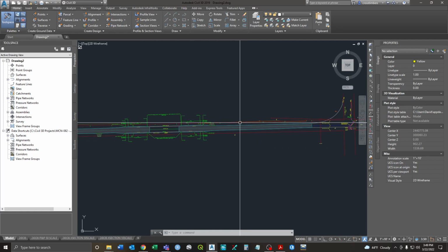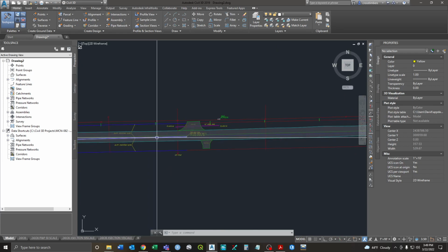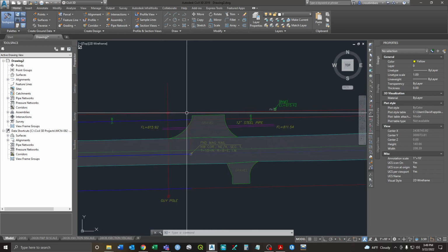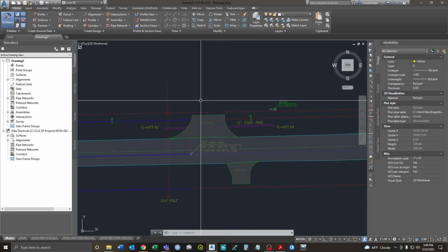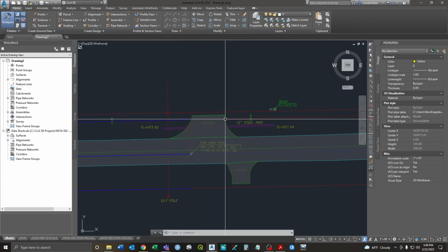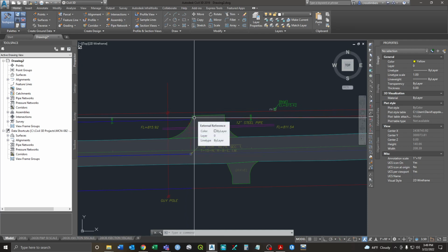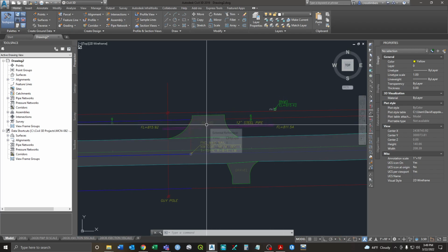So those gravel spots there, he doesn't have those on the map to do. Or do I do those gravel spots as well? So this is where you're going to have to talk with him on the driveways. I don't think he marked any of the driveways. Maybe not. But we'll talk with him and say, hey, look, there's a lot of these driveways that are over the right-of-way line. Sometimes if it's just fixing up the existing driveway, then you don't need extra right-of-way. You just coordinate with the landowner and say, hey, we're fixing your driveway as part of this job. And they're typically just grateful.